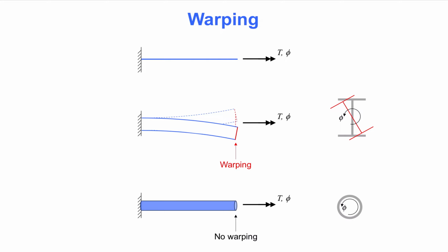The beam with a circular cross-section shown at the bottom of this slide does not satisfy that condition. That is because the cross-section does not warp when the beam is twisted. All points along the circumference of the cross-section have the same axial displacement. We will soon review which cross-sections warp and which cross-sections do not. However, let us mention the second condition that must be met before torque is carried by axial stress, namely that we must restrain the warping somewhere along the beam.